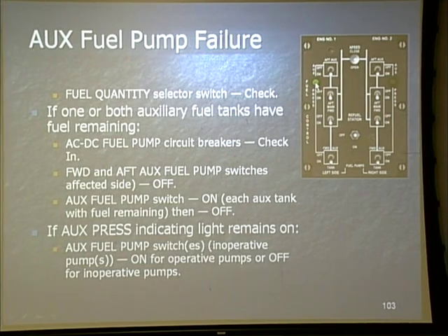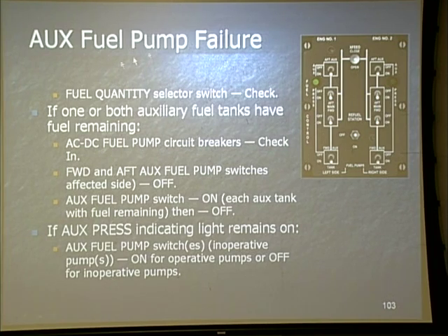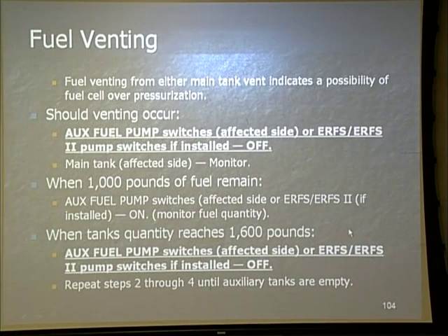Aux fuel pump failure, keeping in mind, how do we determine a failure of the pump versus an empty aux tank? If I get this light in conjunction with fuel remaining in the tank, then it's the pump that failed. Now what do I need to remember? That fuel is now classified as unusable. Any questions about that? If I get this light and there's no fuel remaining in the tanks, then the tanks are empty, and that's okay. It did its job.